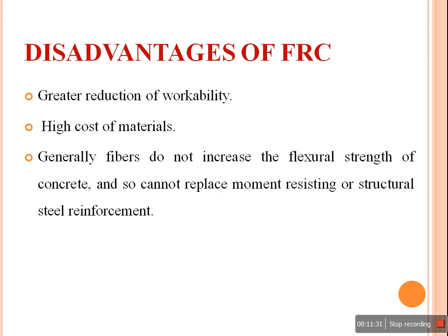So every material has some advantages and disadvantages. So what are the disadvantages of fiber reinforced concrete? That is a greater reduction of workability, which is the foremost important character of concrete, so which has to be taken care of. Next one is the high cost of materials.